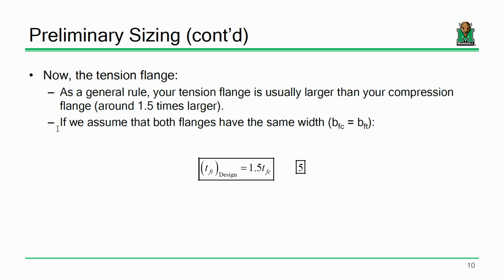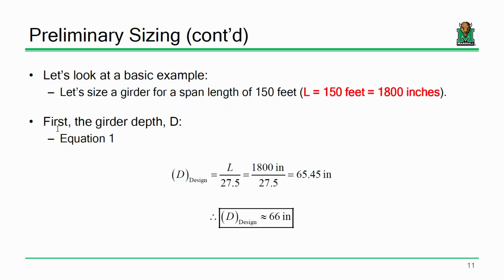That's another thing that's a little different when you're looking at plate girders, for instance. With plate girders, usually the flanges aren't the same size. They're different because you're tailoring each flange to a given demand. So your girder isn't doubly symmetric, but that's common.